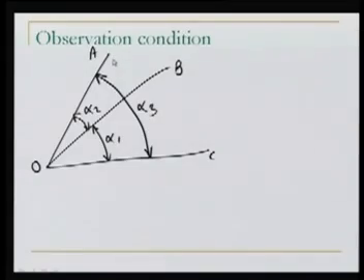Now just think of the case of the theodolite. What do we do with the theodolite? We set the theodolite at point O. It should be exactly above point O. The vertical axis of the theodolite should pass exactly over the point O. Will it be so? No. There are problems in centering. We cannot center truly. There is some error.